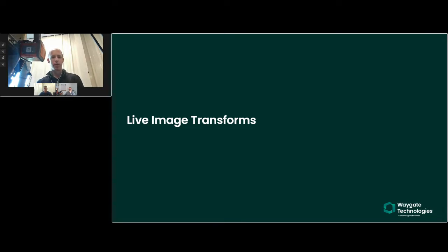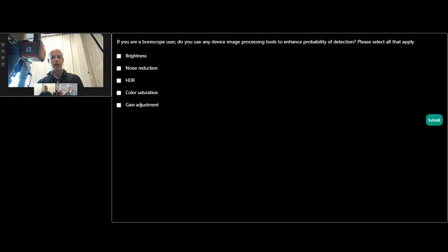Before I jump in, if you could do me a favor and just go ahead and answer this first poll question. If you're a video borescope user, do you employ image processing techniques to improve your probability of detection? I've listed a few here. So you have brightness, that's obviously increasing the brightness of your video borescope, the auto gain and exposure levels.